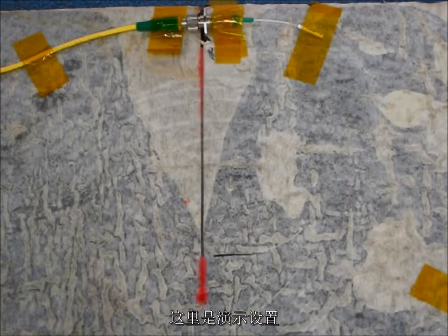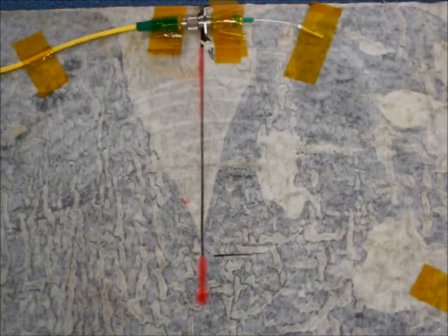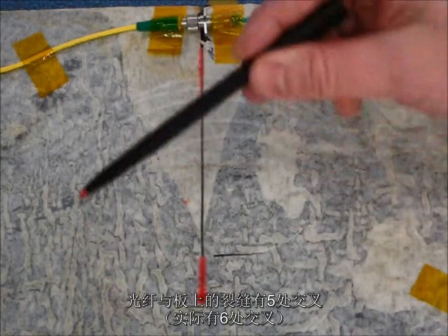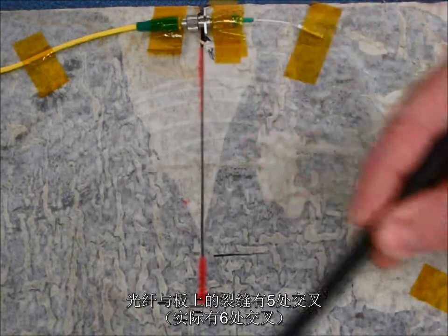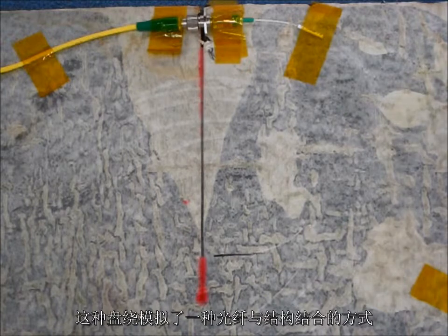So here we have our experimental setup to demonstrate detection of the formation of cracks within a structure, such as a road or a dam and so forth. We have a sheet of plastic here to which we have bonded an optical fiber around in a series of 5 loops. 1, 2, 3, 4, 5, in a manner similar to what someone would apply a fiber into a structure.